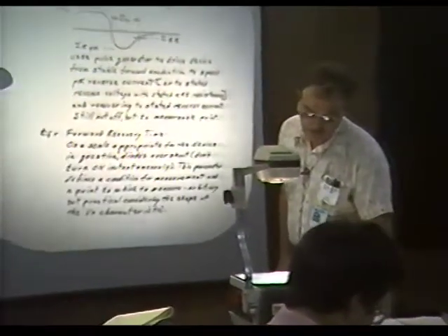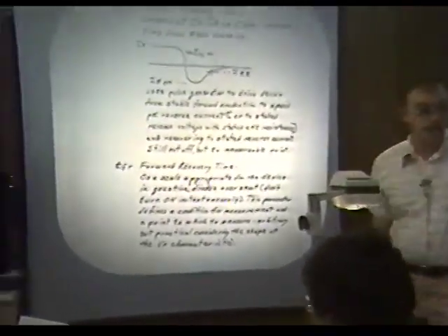And on the smaller devices, at least, normally this is specified. Normally given at zero bias. It is a function of bias and decreases with increasing bias. If that's a mystery, that's because this depletion region he was drawing is becoming wider as you increase the voltage, so the capacitor plates are further apart and the capacitance goes down.